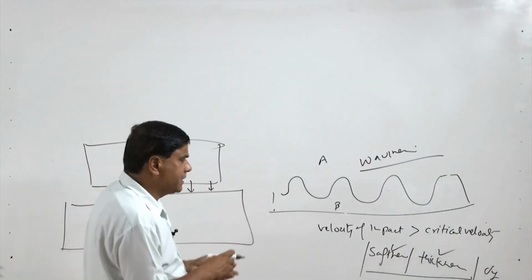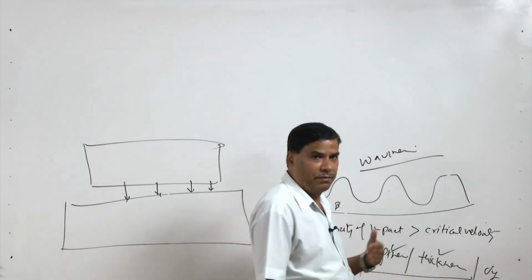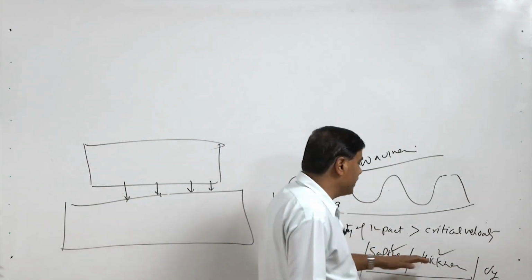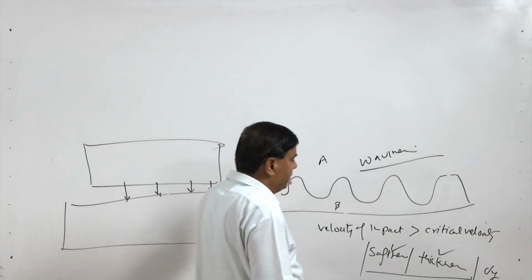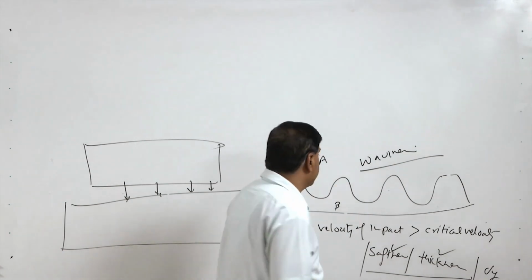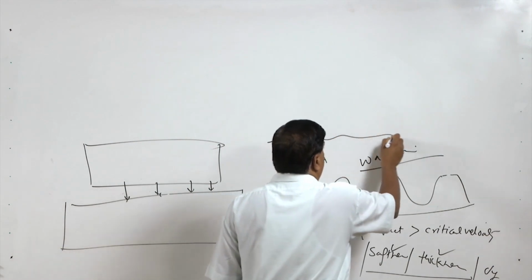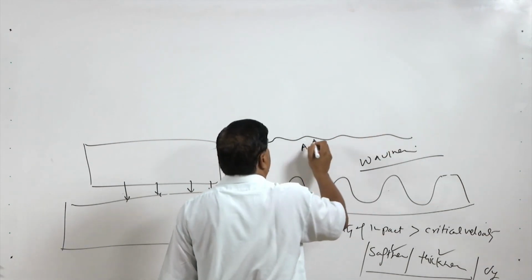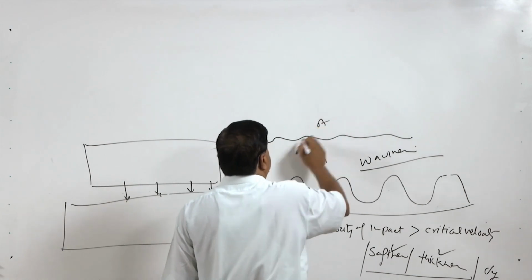The greater the resistance to plastic flow, the higher the hardness; the lower the hardness, the softer the material, and the easier it will flow. So, thickness, yield strength, and softness will determine the critical velocity at which the waviness will be present. Otherwise, the interface can be literally flat, with A on one side and B on the other.